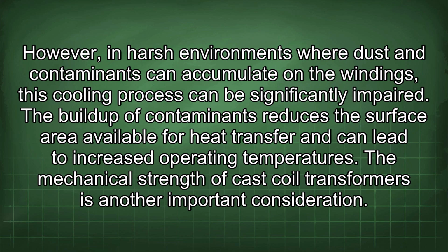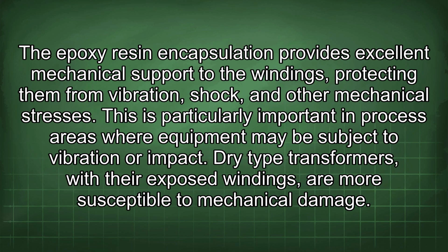The mechanical strength of cast coil transformers is another important consideration. The epoxy resin encapsulation provides excellent mechanical support to the windings, protecting them from vibration, shock, and other mechanical stresses. This is particularly important in process areas where equipment may be subject to vibration or impact.